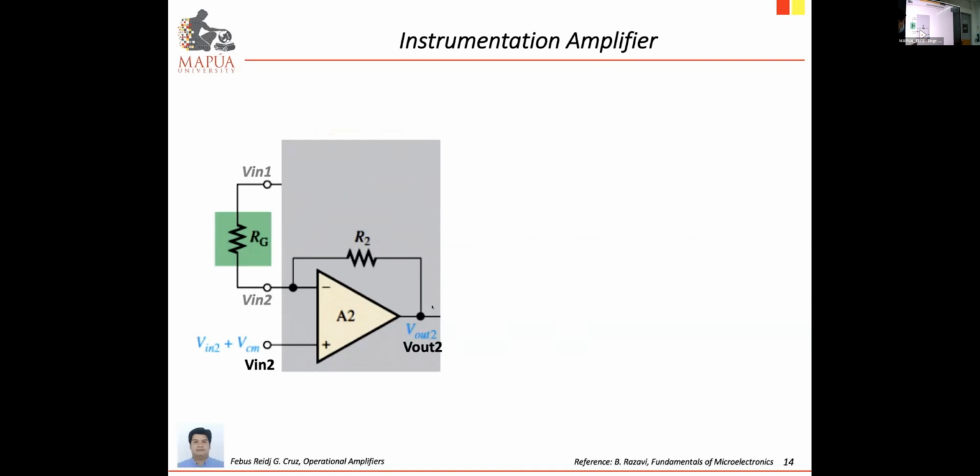Right? So from the actual input, V in 2, the input current will go out, and some of that current will return passing through the feedback resistor R2. And then on this node, the feedback resistor will again be input to the op-amp and current along gain resistor RG. Then apply KCL on this node.